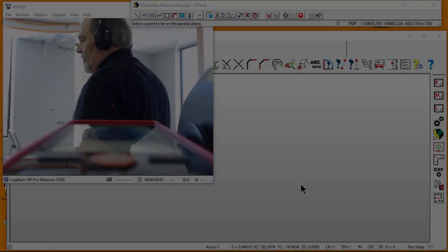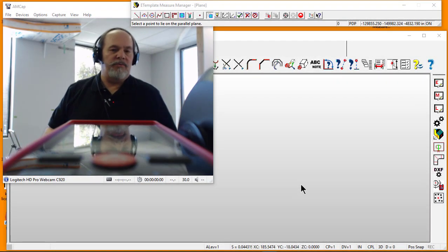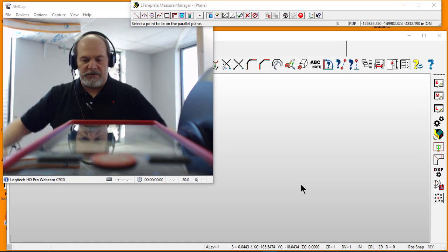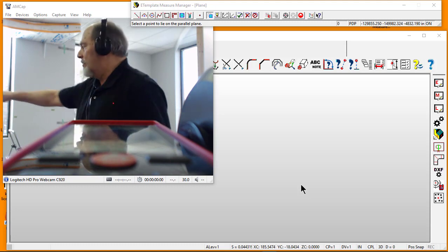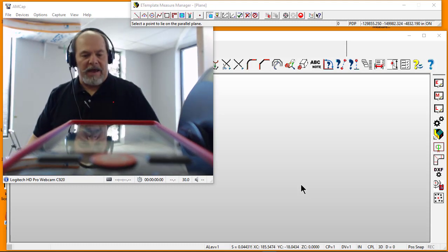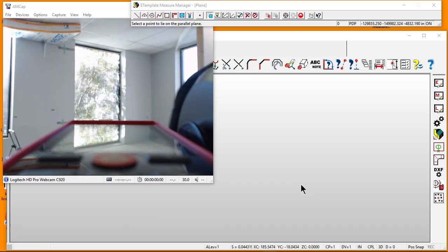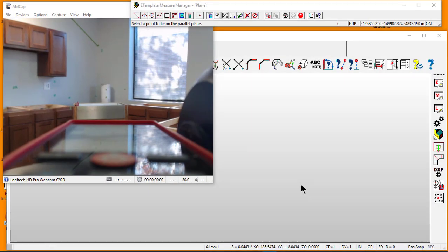when we're drawing. Now because we're going to do a 3D room, we're going to drop the plane, the construction plane from here, we're going to drop it to the floor. That way as we do the perimeter, we're doing the perimeter at the floor level, then we can extrude it up to the ceiling height. So let's do that. So you can see it back in that shadow of that column.